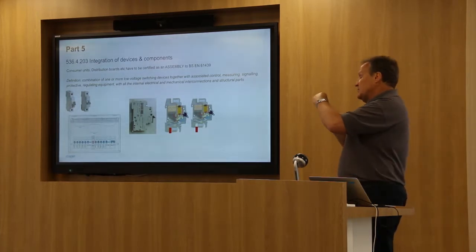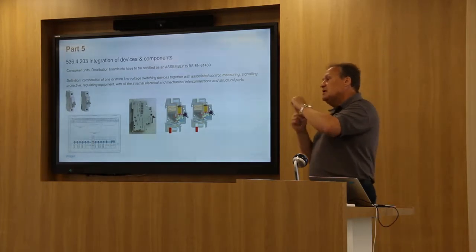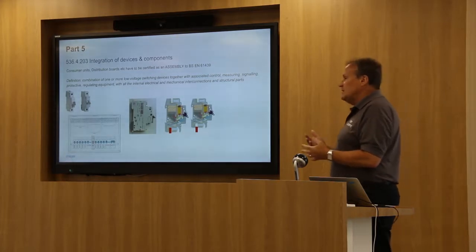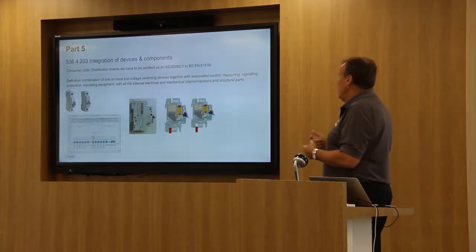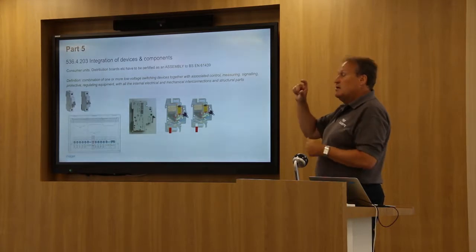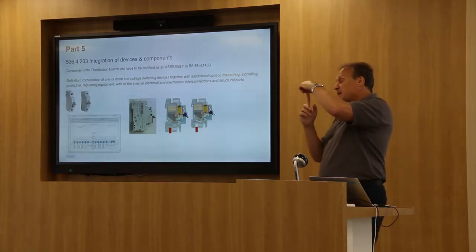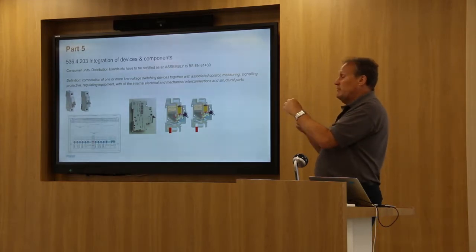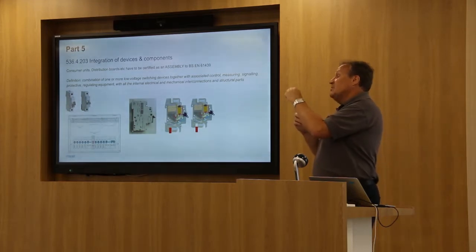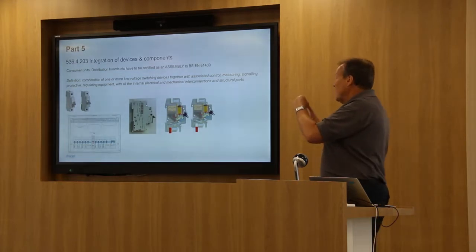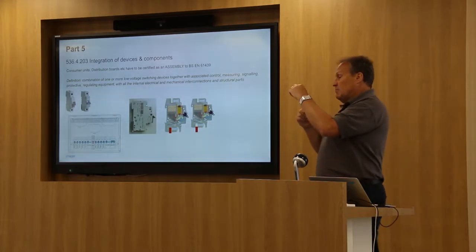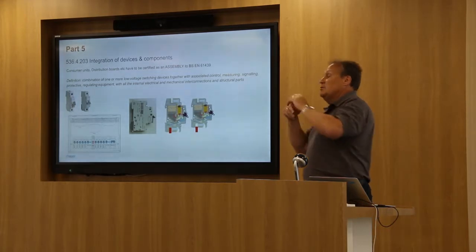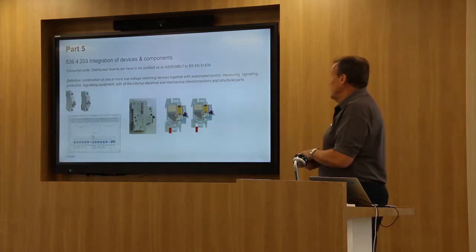So just imagine that a circuit breaker of ours on the left there has the busbar nicely fitting inside the terminal, gives a good electrical connection, and doesn't generate a lot of heat. But it's been substituted, for whatever reason, because that's the only one you had in the van, by one from a different manufacturer that was slightly shorter. You can see it might just be nipping the busbar. So if you do your electrical test on that, an earth loop impedance test or whatever, you're getting an electrical connection, but you're not getting a good electrical connection. Once that's under load, this bad electrical connection is going to generate heat. It could generate too much heat, and ultimately it could generate fire.